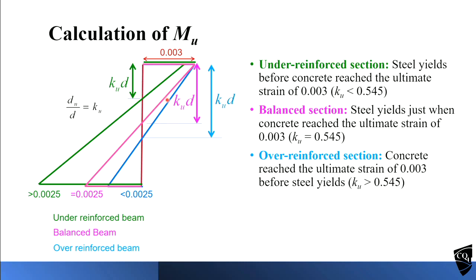Okay, so this is called under-reinforced, balance, over-reinforced. So we would like to have everything under-reinforced, but remember, for the ductility we have further down. The ductility requirements are set by standards. This over-reinforced, balance, these ones are set based on the strain values.